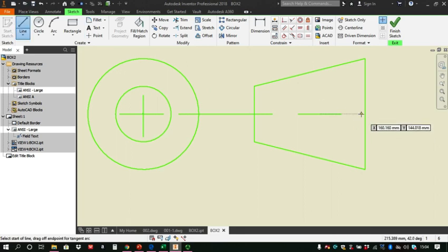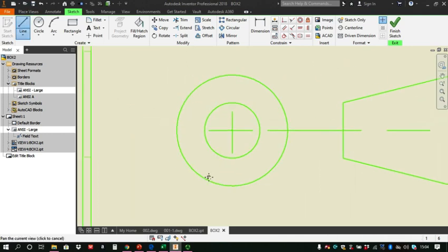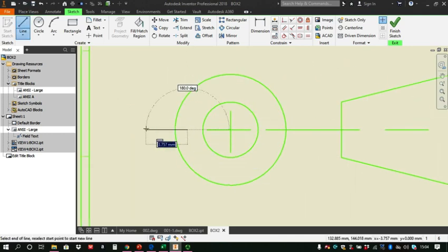And is anybody going to pick up that these aren't the correct centre lines? And the answer to that's not really. Nobody's going to be bothered. They know what the symbol means. It's there. It's good enough. But if you want to draw exacting and use exacting centre lines, you can be my guest. Nobody's going to stop you doing that either. But this is kind of a quicker way of doing it.